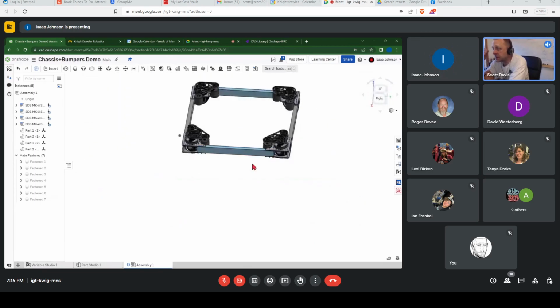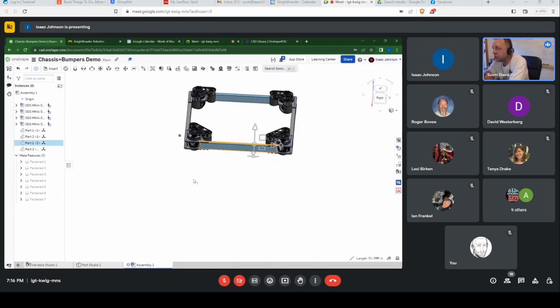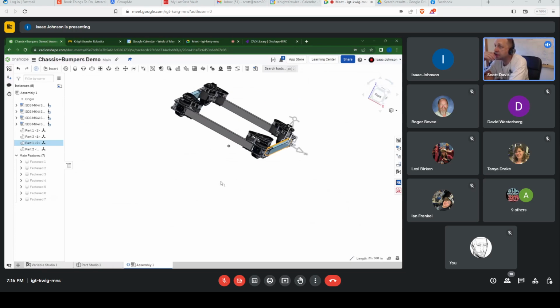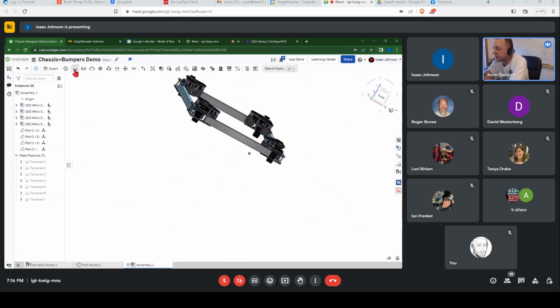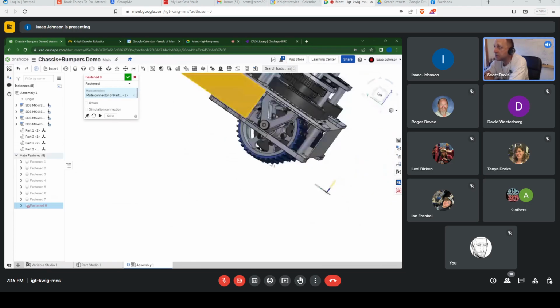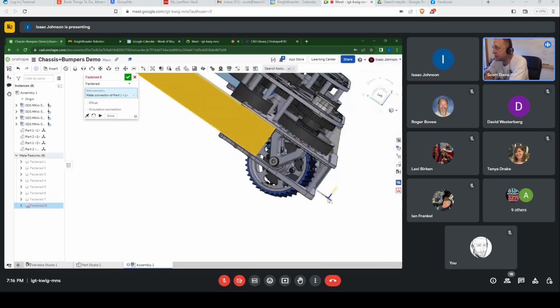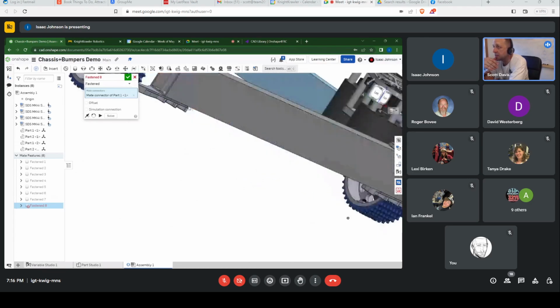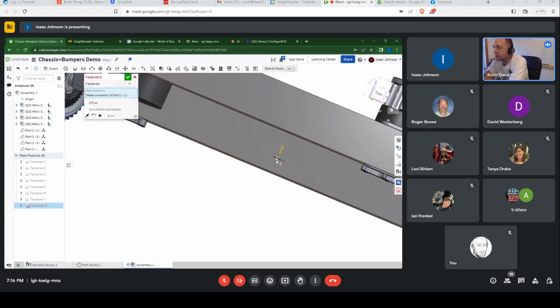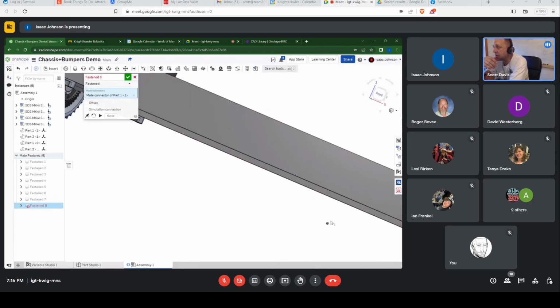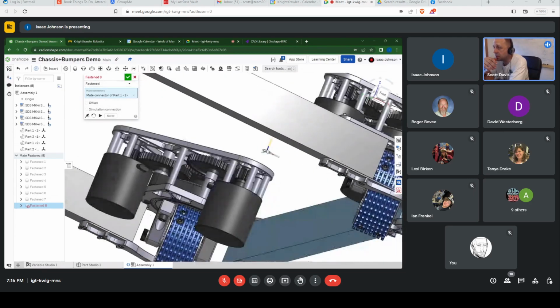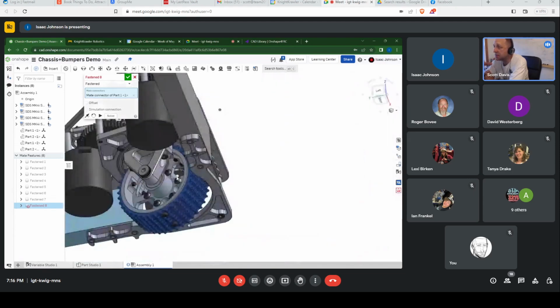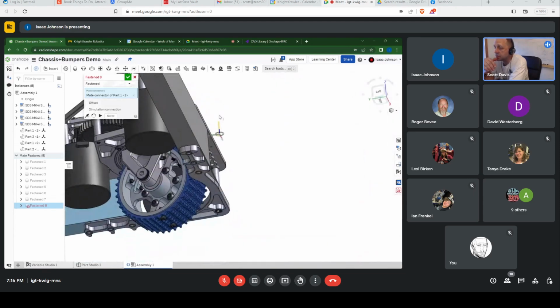And that's really great. In fact, when I started learning CAD, I was going through the OnShape tutorials, and it was basically how would you build solid shapes from scratch. And I thought to myself, how in the world am I ever going to design a robot? And then I started watching tutorials on how to do FRC OnShape, and it's like, oh, you just go get all these pre-built modules that someone else has put together, and all you have to do is stitch them together. And then the only thing you have to make from scratch is your plates that you would cut on a CNC or the box extrusion that you would cut.